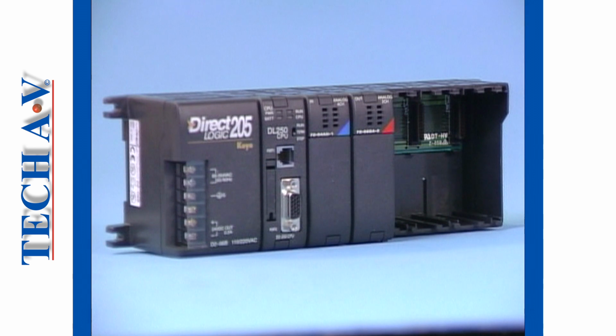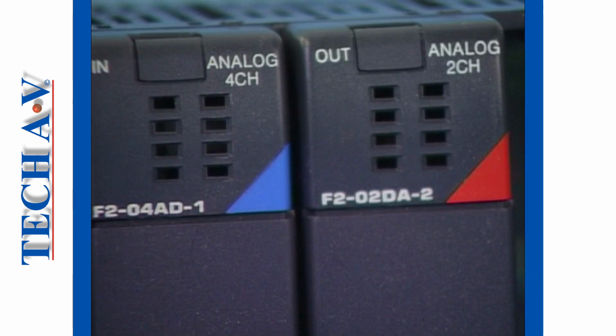When we use analog input devices, special input modules are required by the PLC to convert the analog voltage signals into numbers and then into simple on-off information signals that the logic section of the PLC can understand.